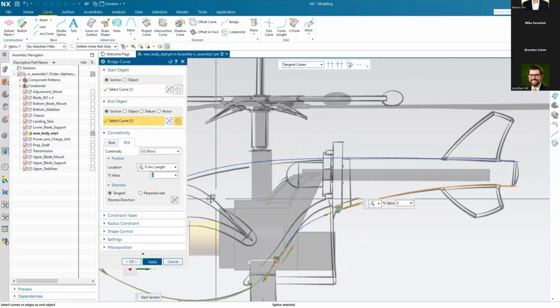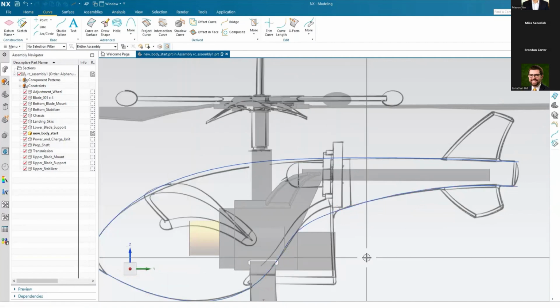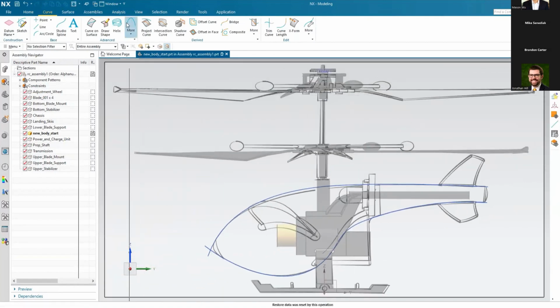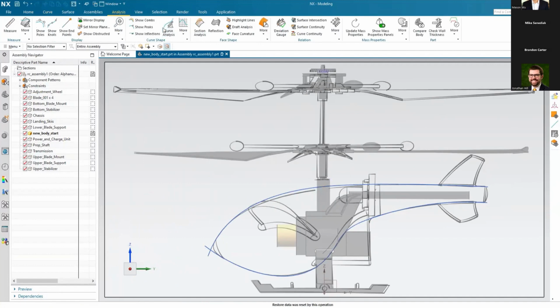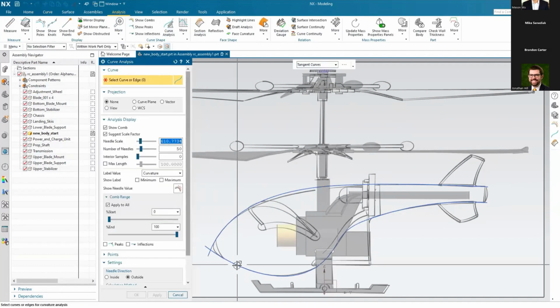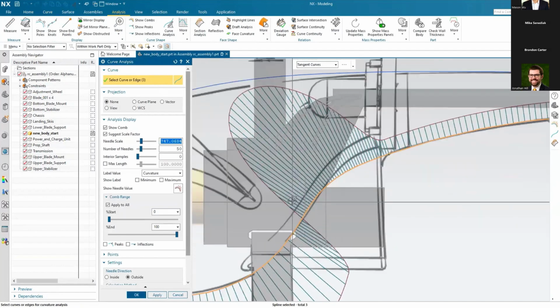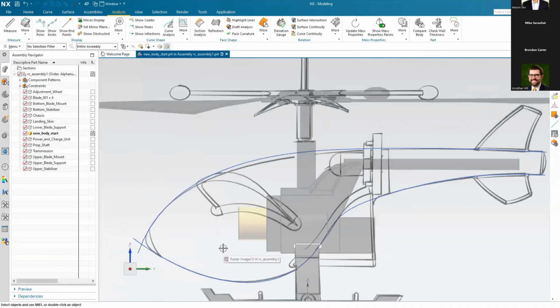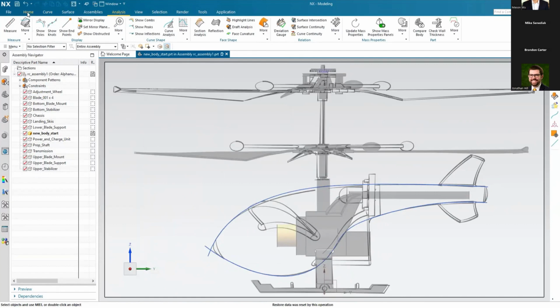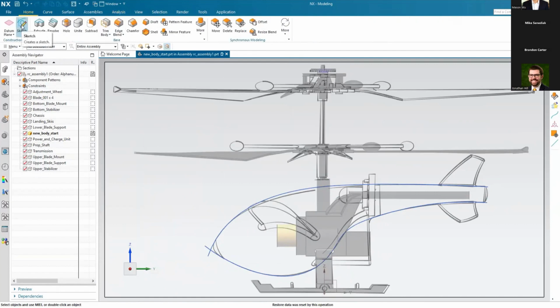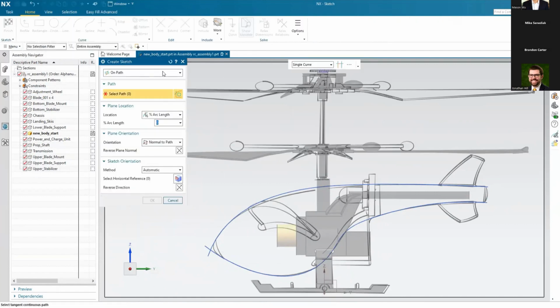By completing the steps, and again, if you're familiar with NX, the dialogues are already driven by, hey, there's a little red asterisk. Those are things you have to complete. And then when you've satisfied that, you'll see the green check marks, not only in the dialogue, but also on the screen. So there was a different way to show that continuity. We saw that there were no breaks in that spline that may cause us to have poor surface quality.